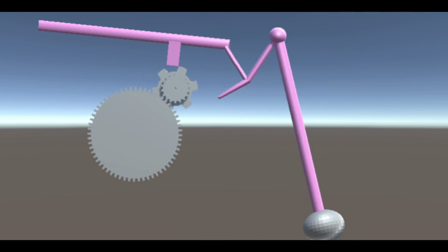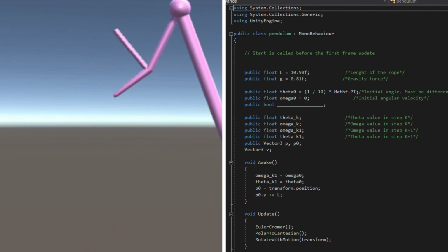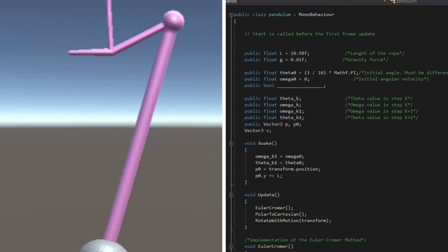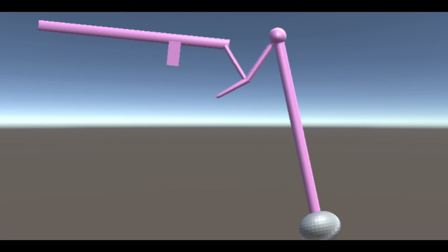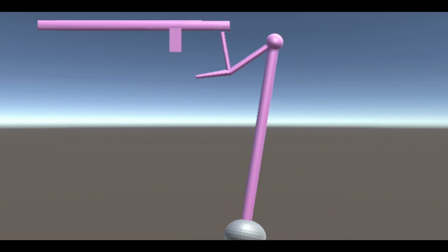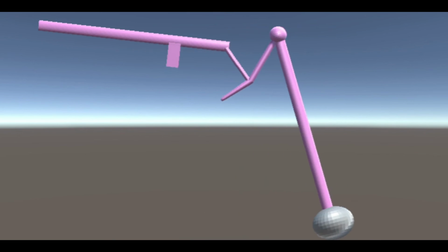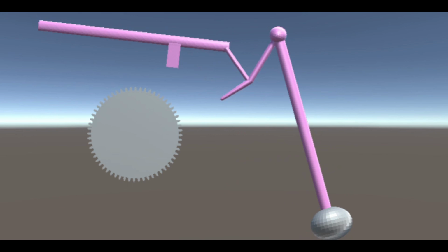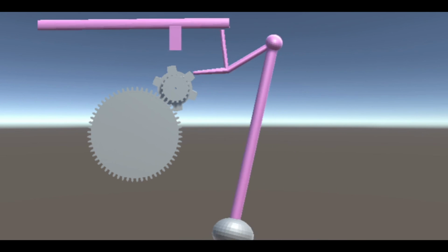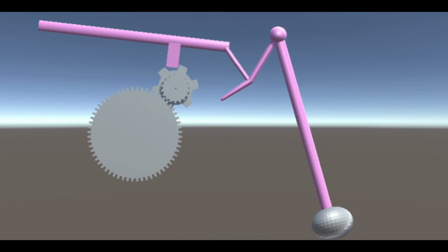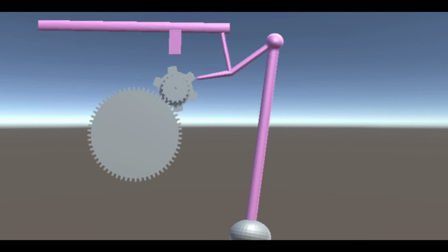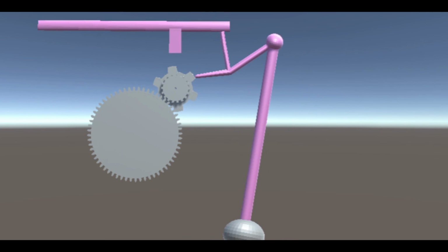When this happens, the gears can freely turn without anything stopping them. However, when the pendulum gets to the amplitude limit, we make the escapement device fall with a tilt angle because one of its tips is a fixed point. This makes the gear's movement stop for a period of time equal to half the period of the pendulum. And that is how we generate the 1 second clock movement.